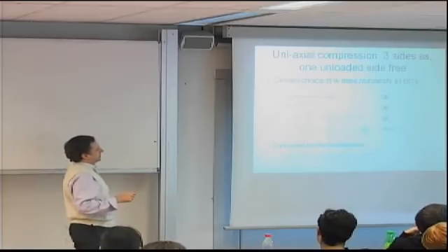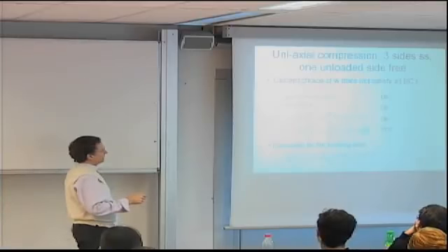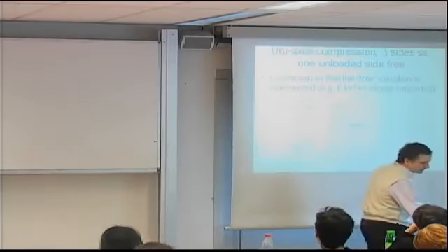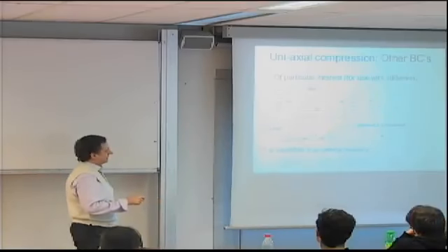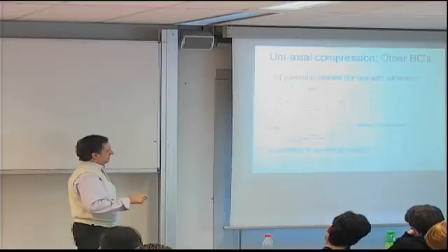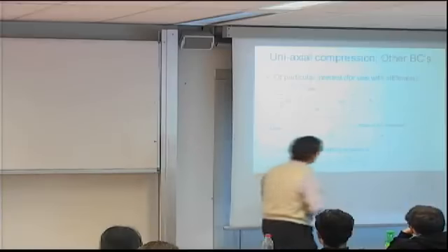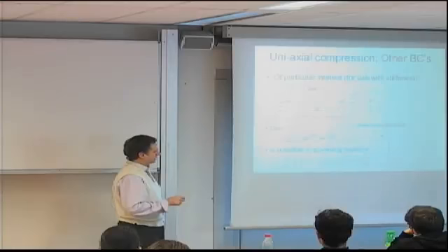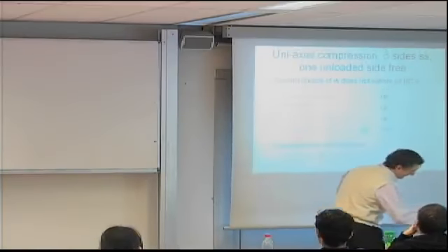Remember, our boundary conditions now are that W is 0 at the 3 edges, not at the 4th. The 3 edges are x equals 0, x equals a, and y equals 0. So for my assumption, if I look at the x dependence, at x equals 0 and x equals a, this is 0. And at y equals 0, the sine of 0 is 0, so I'm fine. Then let's look at the second derivatives real quick. As far as the second derivatives with respect to x are concerned, I reproduce a sine, and this one reproduces the same thing with the lambda. However, the lambda does not give us the values we want.